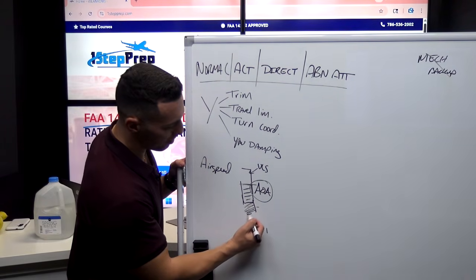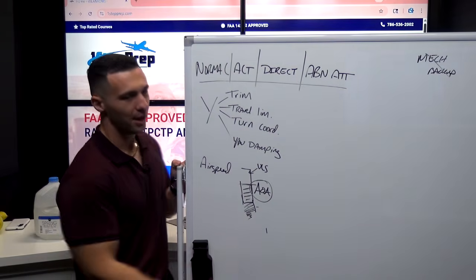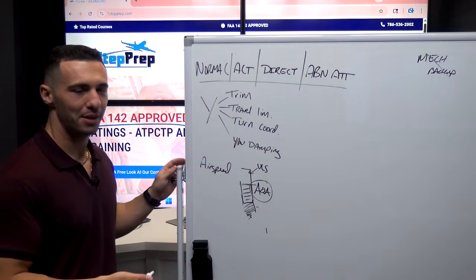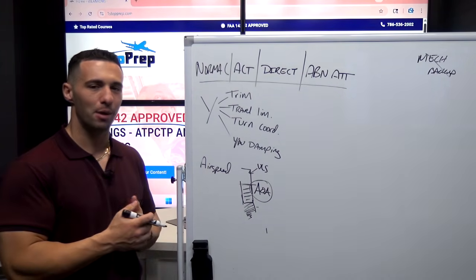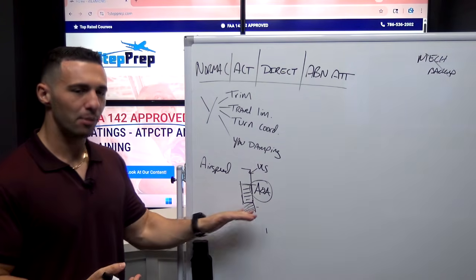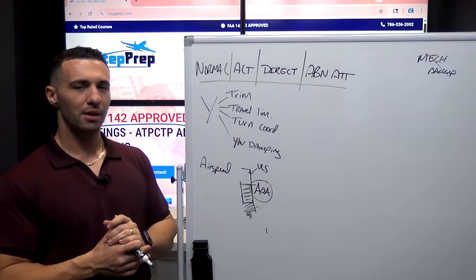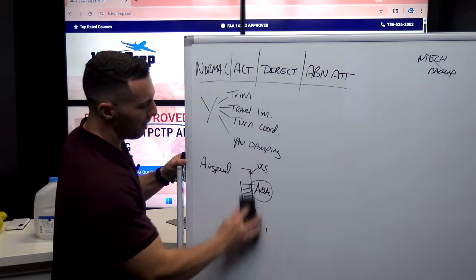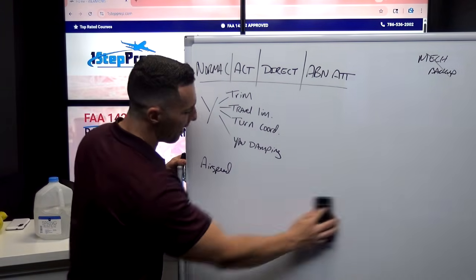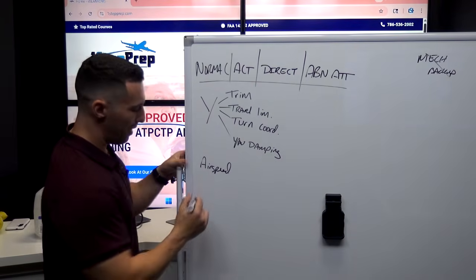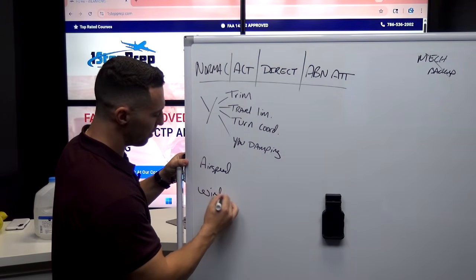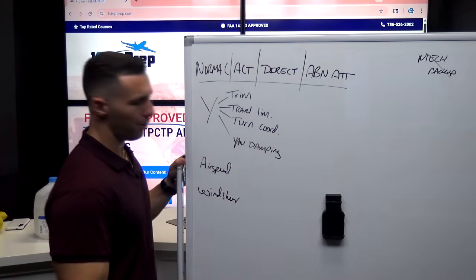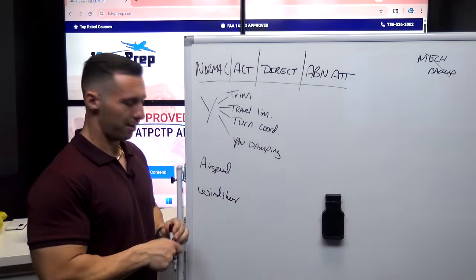And then, of course, the same is true for alpha max. It is also the angle of attack where the flight control computers intervene and prevent stall. So if you ever get there in a demo in a sim, you might be a little bit into it before the actual alpha max activation happens. Okay, so that's your airspeed envelope as it relates to what the FAC gives us. And then we have wind shear alerts. That's another thing that the FAC likes to provide for us, fortunately.